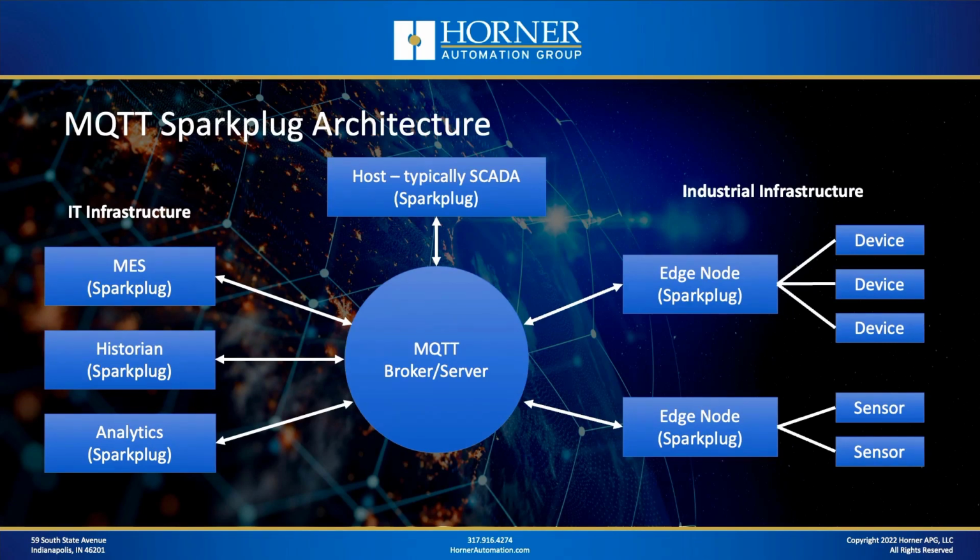And then you'll notice a device at the top that's called a host. And this is a little bit unique in Sparkplug. This is a special type of device that's defined in Sparkplug, and that is a host Sparkplug device. And it's really designed to act in the SCADA role, the supervisory control and data acquisition role that you see in a traditional industrial application.